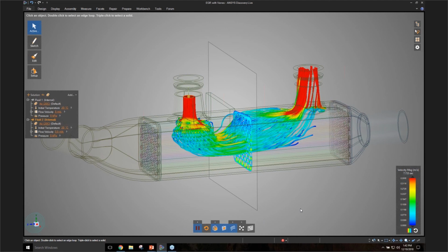Having said that, though, if you're doing a bridge or something like that, or a building, some kind of civil engineering application, beams would be better. It'll be even faster. And if you're doing large fabricated sheet metals, then shell is probably faster. You want to avoid those kinds of applications for Discovery Live. Discovery Live is basically for situations where you have solid 3D geometry, not shells, beams, or zero thickness surfaces and stuff like that.